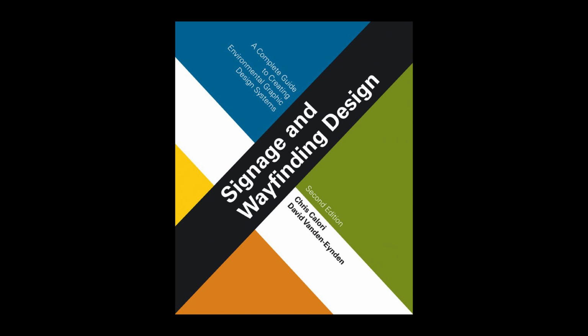Chemical etching and sandblasting are used to create frosted glass finishes, with chemical etching producing a finer frosted texture than sandblasting. Note that there are some considerations in applying frosted finishes to tempered glass. Mechanically produced scratch finishes are not typical for glass.